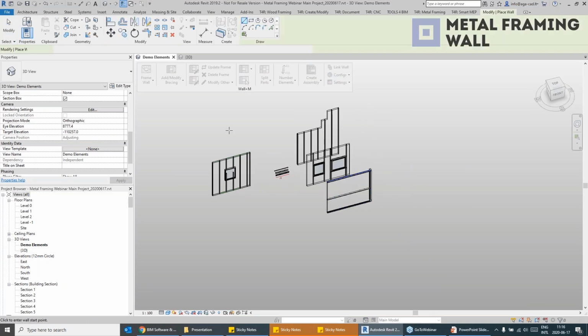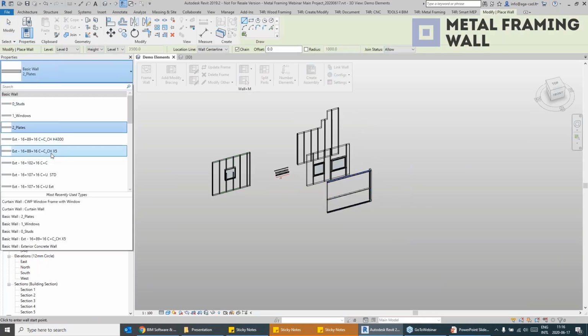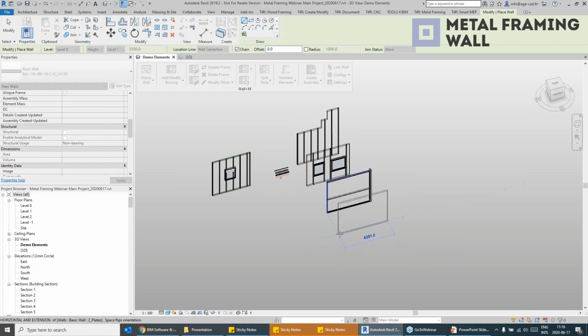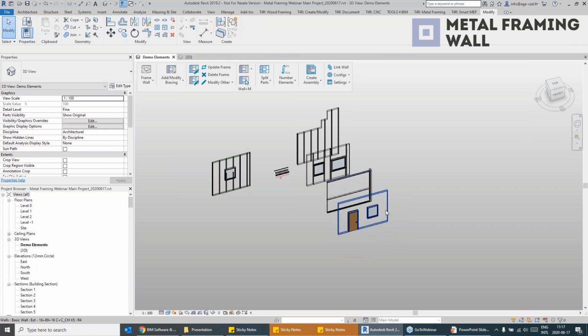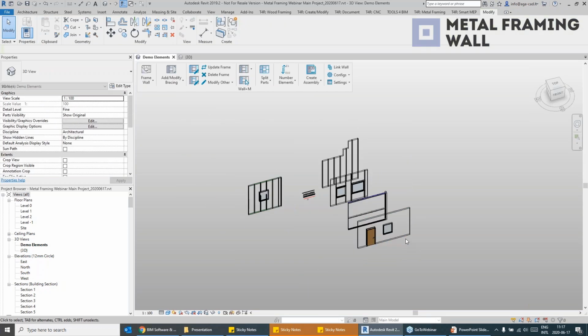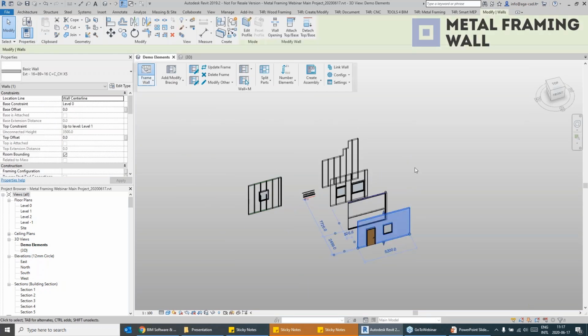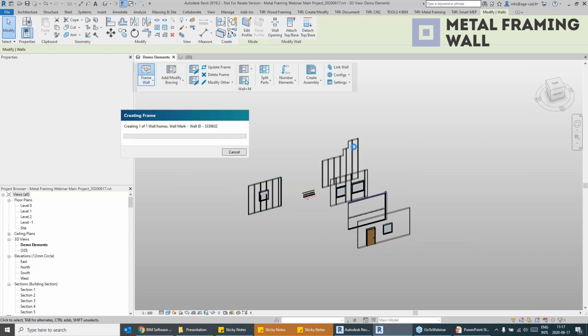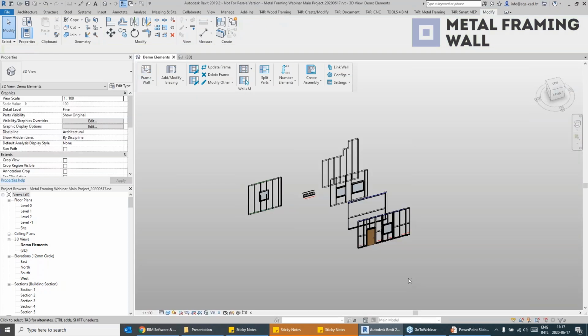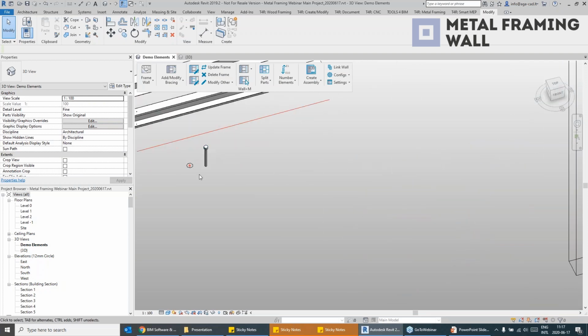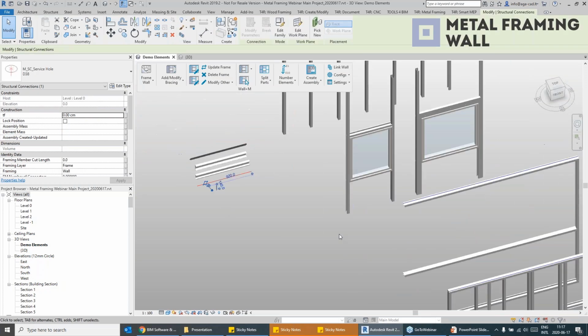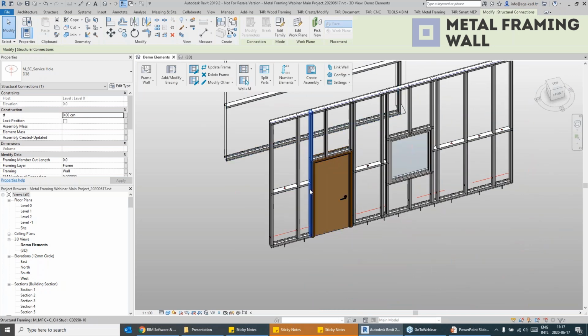And later, I can combine all those rules into one. So let's say I'm having that wall right here. Maybe let's have it with a door and the window. I can actually make it longer. And again, just in one click, I get my studs, my openings as well as my plates combined into one piece, and just in a matter of seconds I'm getting that frame with even the details like anchors, I know, and service holes placed into my frame.